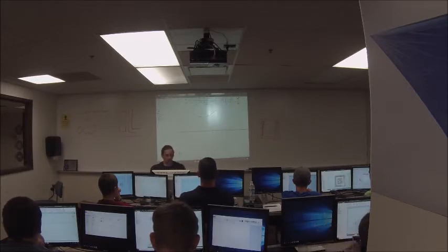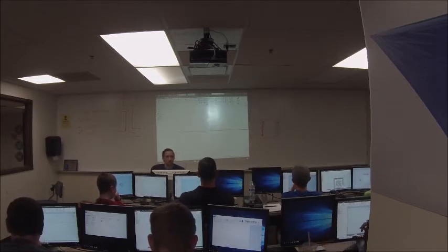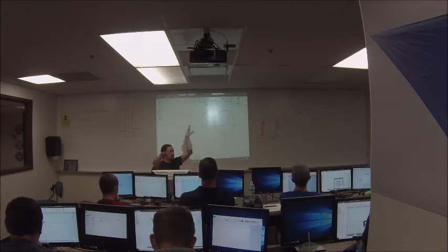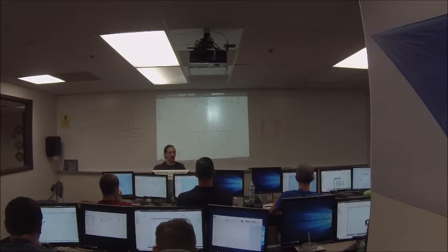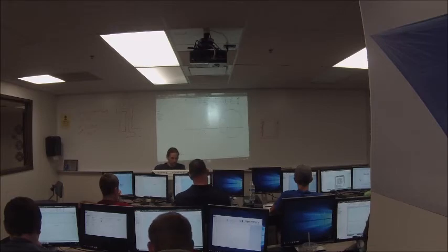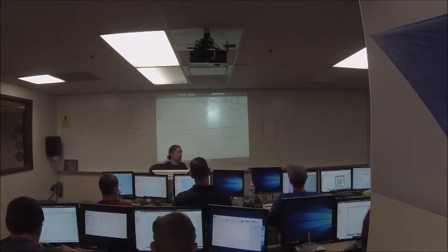Okay, so I'm going to undo this. I can also do a vertical constraint, which obviously does the opposite, makes things vertical. Now this has another use too. So if I have two circles, say, in different places, and I want them to be in line horizontally, I can click the horizontal constraint, click the center point, and click the center point of the other one, and now they're lined up horizontally. And I can do the same thing vertically as well. I'm sure you guys can imagine how that works. Okay, so that's how horizontal and vertical work. They're pretty versatile.